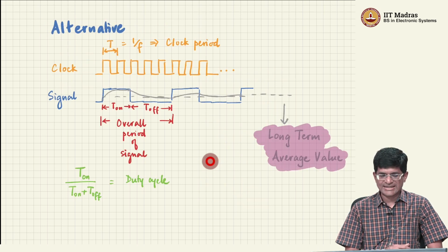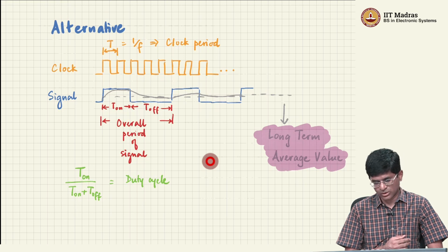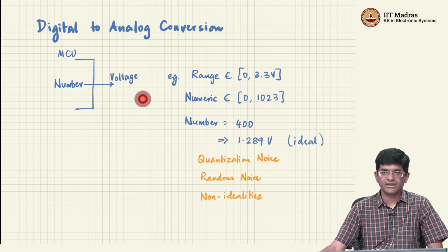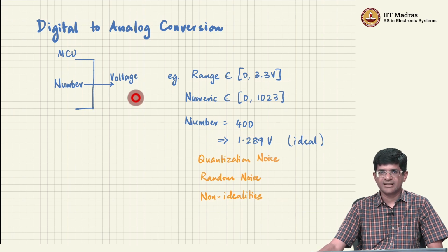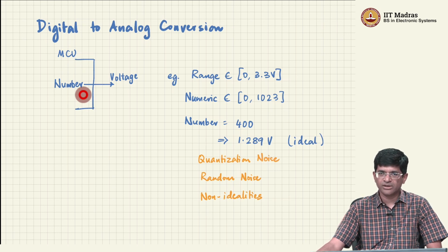So the bottom line is, yes, just like we built analog to digital converters, it is possible to create digital to analog converters as well. They would take in a number and generate a voltage that is proportional to that number. The point is, in a lot of cases, that's a bit more complicated than we really want. The circuit for doing the digital to analog conversion is not a very trivial circuit. It does require a certain amount of work. It's not the most complex circuit in the world, but we would like to simplify if we can.